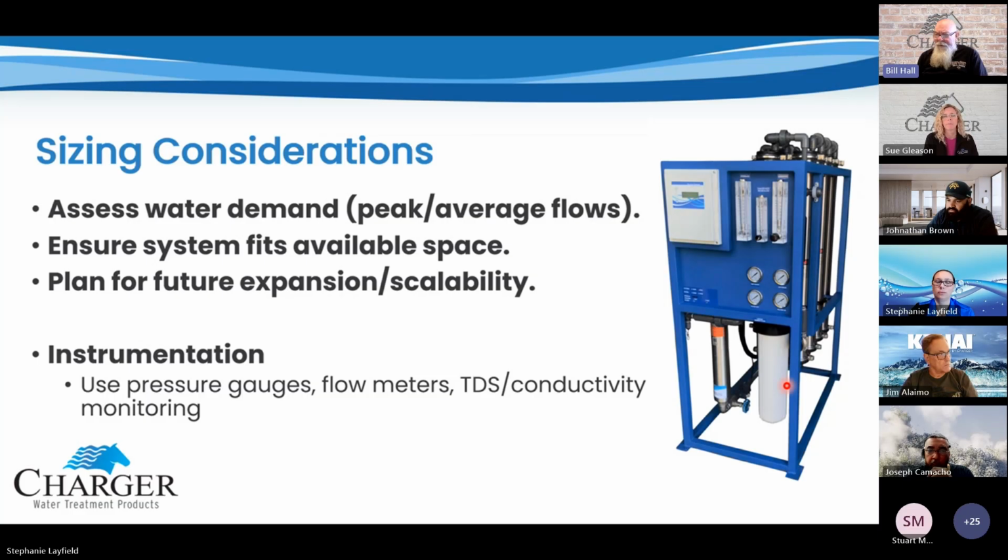Some of the things to keep in mind, especially when we're talking about performance on these things, is what Stephanie touched on, SDI. Take a look at the spec sheet on the membrane itself, and it'll tell you down at the bottom that the performance is based on a water temperature of 77 degrees, TDS of X amount, maybe 250 parts of sodium chloride, it may be 500 parts.